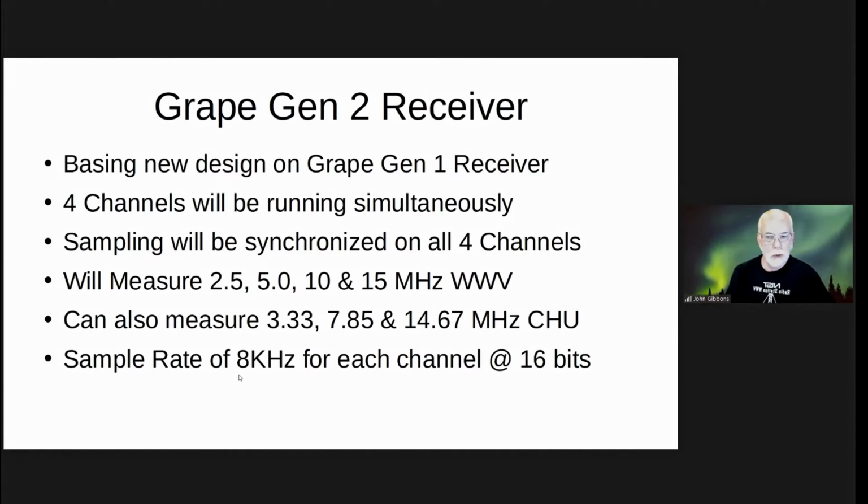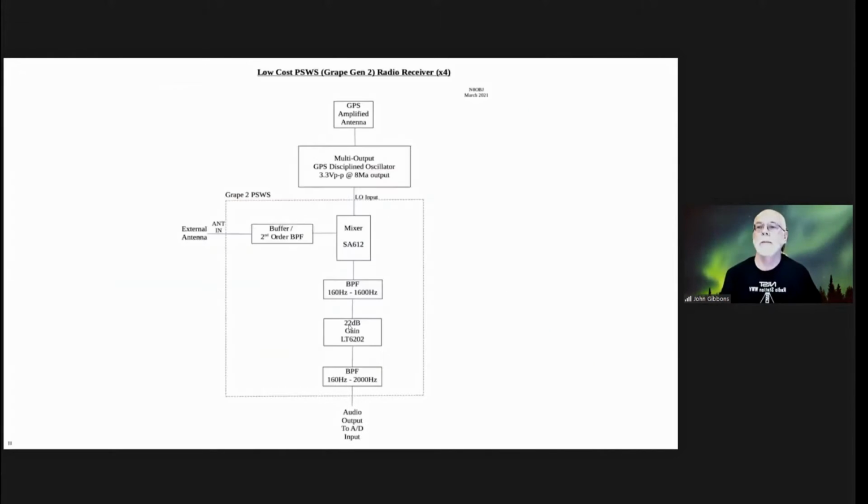And it's important to note that this 8 kilohertz sample rate is critical to be accurate, because that is how we're determining the frequency. So if this is running too fast, it's going to push the samples closer together, and it's going to make the signal look like it's lower in frequency. So there's a direct correlation between having this accurate and having everything else work correctly.